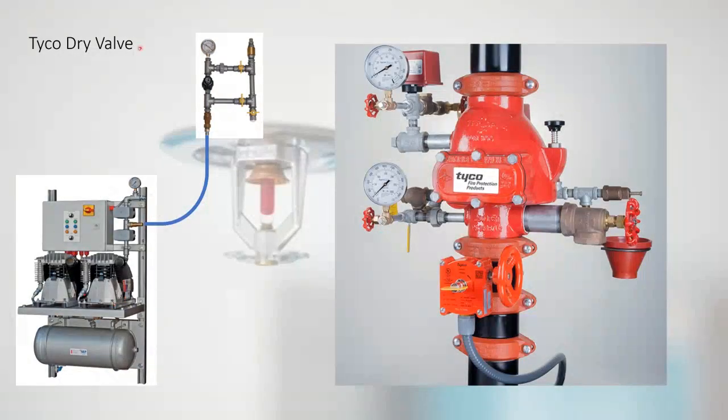Now the air maintenance device has got two valves. Okay, that valve is usually open. Okay, and that valve is usually shut. And that valve is usually open. And the idea is that that's your pressure relief valve. That tells you what the pressure is, and that maintains the air in the system. Now, what you can then do is you can shut this valve. When you're filling the system originally, you can shut that valve and open that valve, and that's a quick valve.